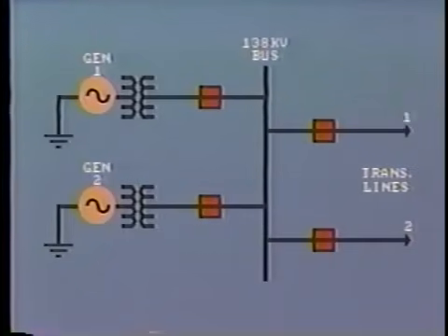Why is this especially so for a bus? Well, look at our simple example. We have 2 close-by generators feeding into the bus and 2 transmission lines taking power from the bus and feeding into the system. If, say, a ground fault occurs on the bus, then we have not only the generators feeding into the fault, but also the power system. The current flow in the transmission lines would reverse and feed into the faulted bus. With such high fault capacity available, the resultant damage could cause a prolonged outage for repair, with the consequent loss of availability of generation and the 2 transmission lines.